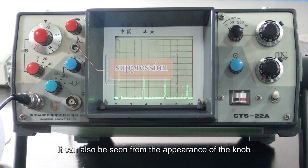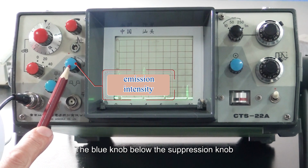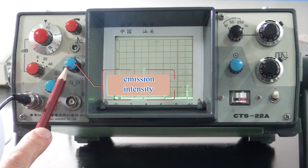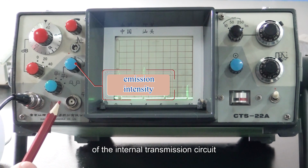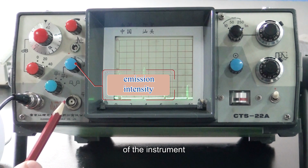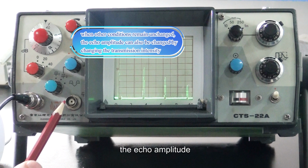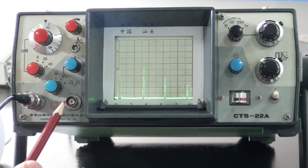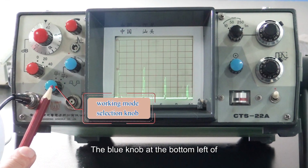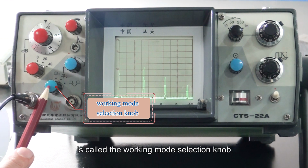It can also be seen from the appearance of the knob. The blue knob below the suppression knob is called the emission intensity. Its function is to change the signal strength of the internal transmission circuit of the instrument. Of course, when other conditions remain unchanged, the echo amplitude can also be changed by changing the transmission intensity. The blue knob at the bottom left of the emission intensity knob is called the working mode selection knob.